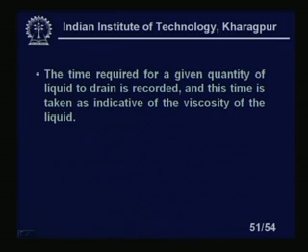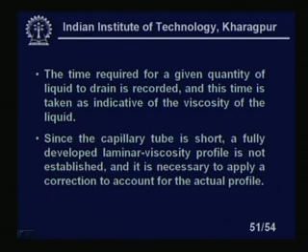The time required for a given quantity of liquid to drain is recorded, and this time is taken as indicative of the viscosity of the liquid. Since the capillary tube is short, a fully developed laminar velocity profile is not established, and it is necessary to apply a correction to account for the actual profile, right.